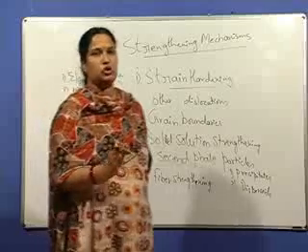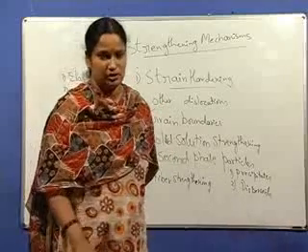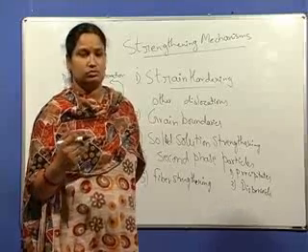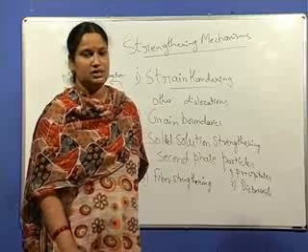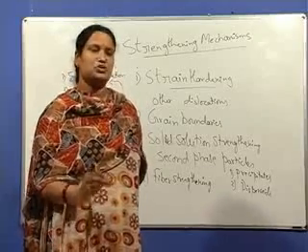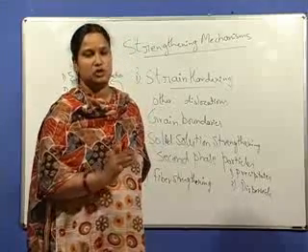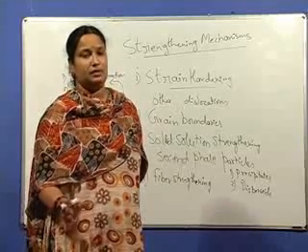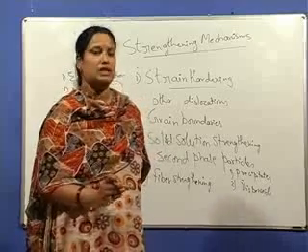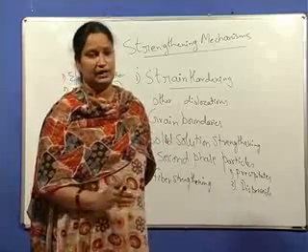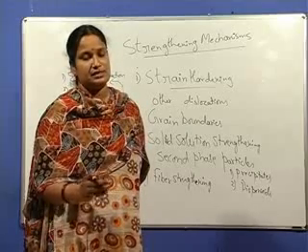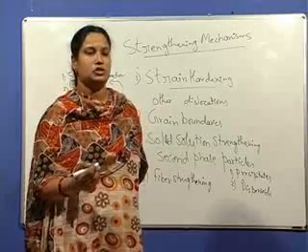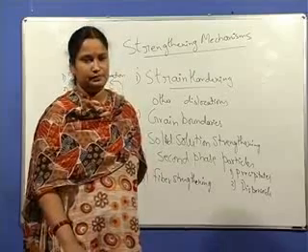Among the two types of solute elements, interstitial and substitutional, interstitial solute elements contribute to more strengthening than substitutional, because they cause more distortion. The distortion created by interstitial solute elements is of non-spherical type, whereas in the case of substitutional, the distortions are spherical.